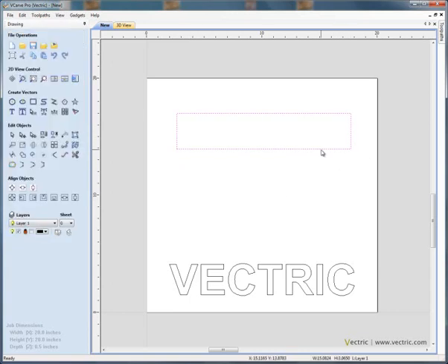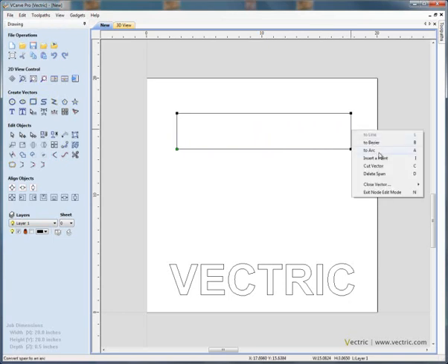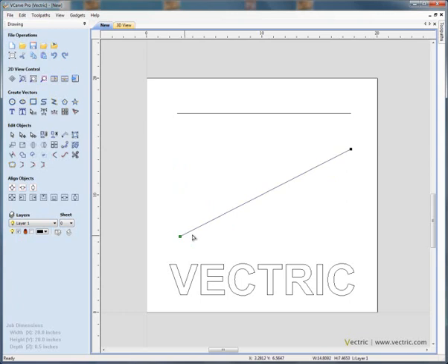Go to node editing, place the cursor over the vertical span and press the letter D to delete that span. We can select this drive curve, click and drag, move this point down. Convert this to a Bezier span, so place the cursor over the span, right click, Bezier. Let's make this a curve like so.